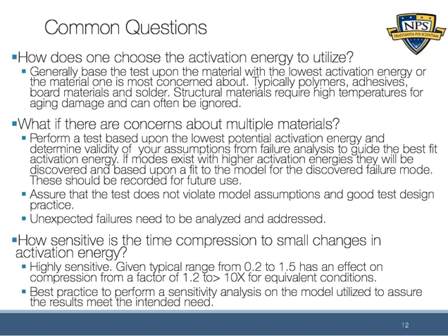The final point here is specifically about the sensitivity of the activation energy. And it turns out that it is actually pretty sensitive. Highly sensitive might be a stretch in terms of the semantics here, but changing the value of the activation energy can certainly change the results. It's good to know, though, that by changing the activation energy, you're essentially saying that you have a different material. So that's a pretty fundamental change. The point being that you want to be aware of choosing the right activation energy. And to be honest, in practice, it's not all that easy.